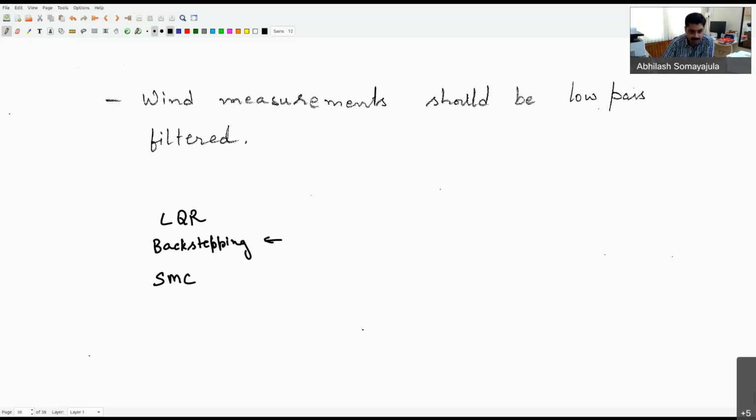Also, another topic here which I kind of forgot was MPC. This is called model predictive control, which means that you have a model of the plant and you're trying to simulate different control aspects. What happens when I try to project it forward into some time and see how the system behaves. Based on that, I figure out how to optimize and take the proper action. So they are all based on some nonlinear methodologies and are going to be computationally a little bit more expensive.